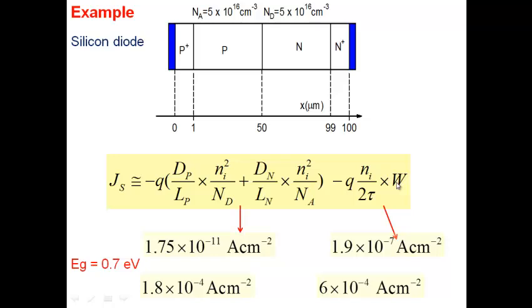Depletion region. Well, depletion region, you would like to keep it small. How do you keep it small? What do you do? Depletion region depends on what? For a fixed applied bias, depletion region depends on the doping. So you would like to keep the doping high, right? So doping high, depletion region becomes small, but doping high is making your tau problematic, right? Not only that, we'll see later on, if you're interested in reverse characteristics, you want breakdown to be high also. Now, the moment you make doping high, the breakdown voltage goes down there. So you don't want to make doping to be high.